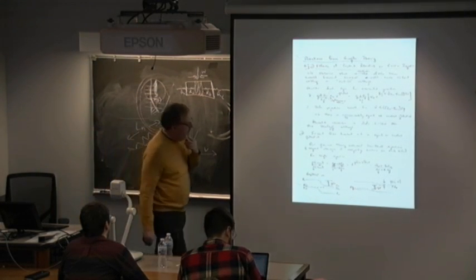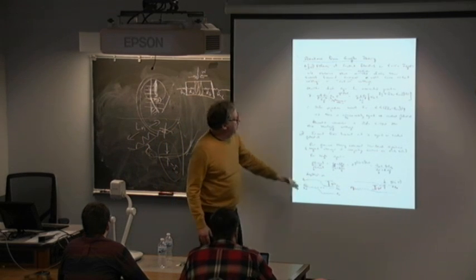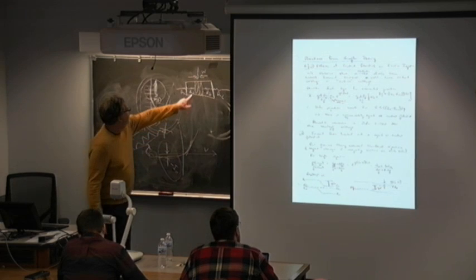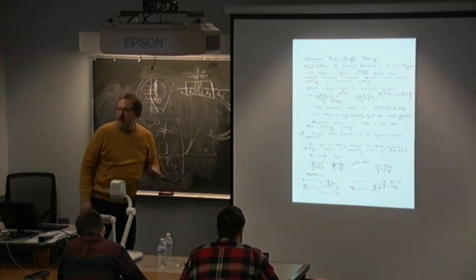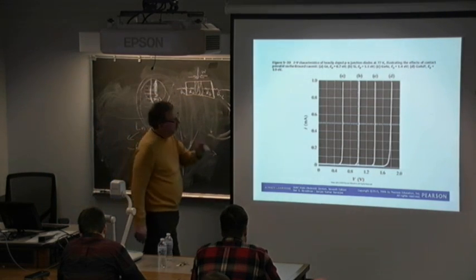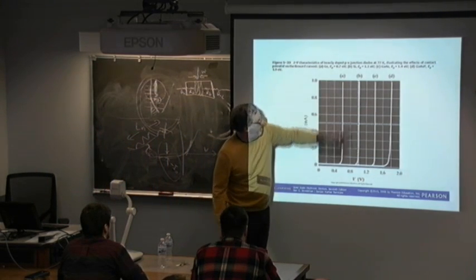Also kind of embedded in there is the idea that you can't go past the diode itself, can't go past the flat band condition. The cut-in voltage also is going to be a function of band gap.